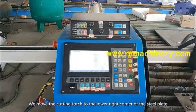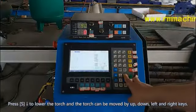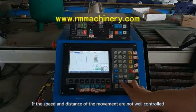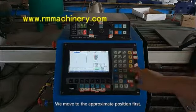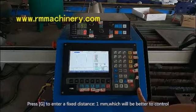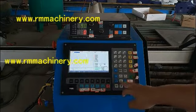We move the cutting torch to the lower right corner of the steel plate. Press S to lower the torch, and the torch can be moved by the up, down, left and right keys. If the speed and distance of the movement are not well controlled, you can press the F key to switch to the fixed length mode to move precisely. We move to the approximate position first. Press G to enter a fixed distance, 1 mm, which is better to control. It will move a millimeter with each press.